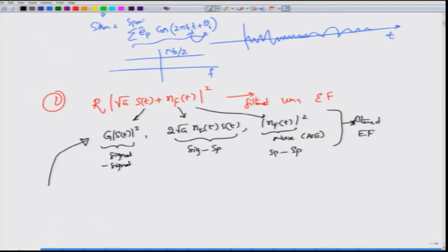We talked about the shot noise and we said that the power spectral density of the shot noise, I am not sure whether we used the same notation as rho sh, but it does not really matter, was given by 2q R P, where P stands for the optical power. So, this is the power spectral density.